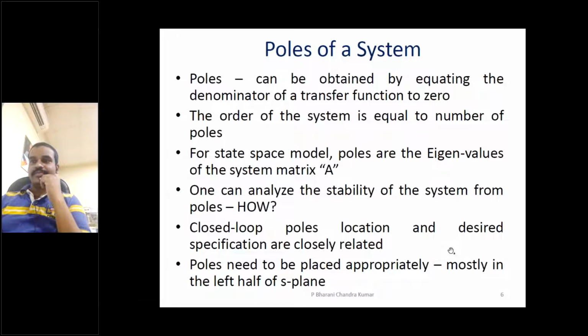We say that pole 12 is an insignificant pole and pole 1 is a significant pole. Why do we say that? Because the 12 is very far away from the imaginary axis, so the time response for that pole, the 12, is very fast.